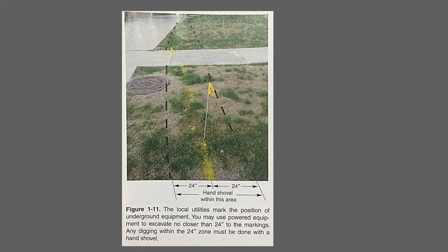The second hazard when excavating is the possibility of a wall collapse. Any trench over 5 feet deep must be reinforced to prevent the sides from collapsing. There are various types of shoring designed to eliminate this hazard. Also, make sure to install barricades and warning signs around the trench. Without these warnings, other workers or passersby may fall into the trench.